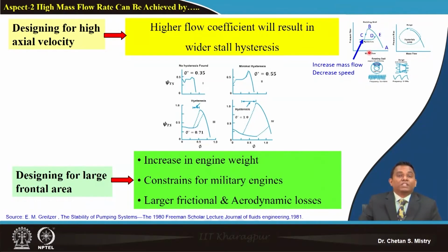Based on the downstream component connected with the axial flow compressor, it may go into a surge condition. So when we reduce our mass flow rate, in place of rising, my pressure will fall down. If you continue running this compressor under that condition, a mechanical failure may happen, which would be catastrophic.